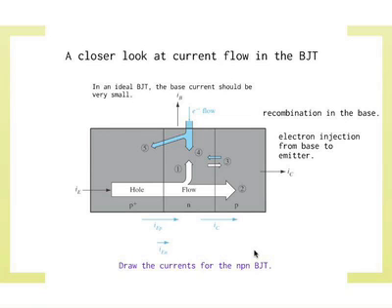Yes? So the current will be less in IC, but the voltage across there, like the voltage output on your resistor, can be higher than the voltage for the control. Actually, let me step back a second. If you use the common base configuration where the small signal goes into the emitter, you do not get amplification at the end of the day. That's the answer. If you want amplification, you need to send your small signal to the base and have a common emitter configuration, which is where we stopped, I think, last class. We'll come to that in a second.